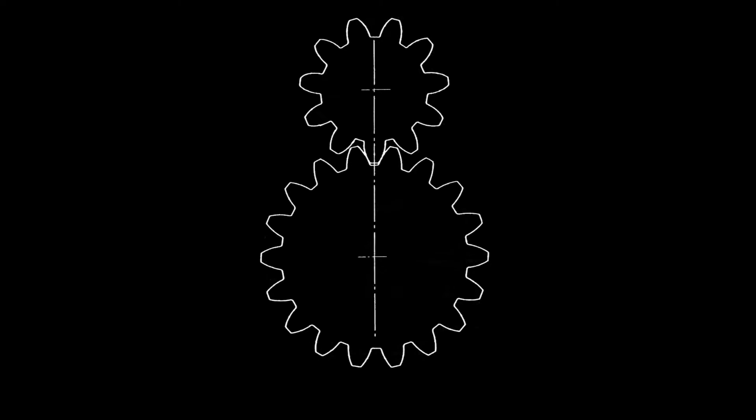In this image you can see a standard gear. Because it's not easy to understand the shape of a gear, firstly some theory. The gear rolls over its pitch circle. The calculations of ratios and forces are all based on this circle. So, it's very important, however you can't measure it on an existing gear.